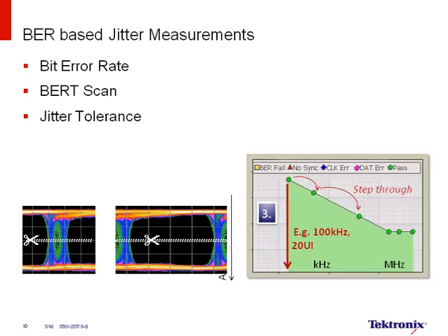In the world of receiver testing, we talk about jitter synthesis, or a jitter cocktail that consists of RJ and PJ to stress the receiver till it stops working. The diagram on the right is an example of that.